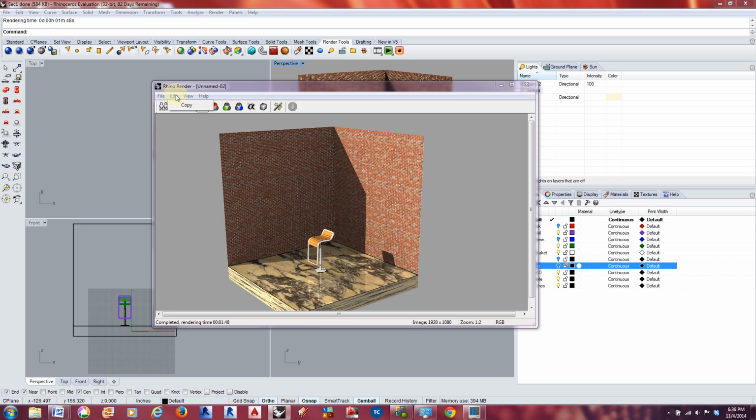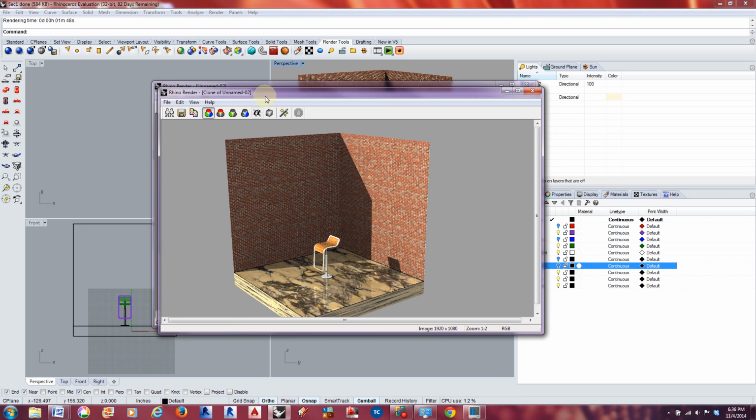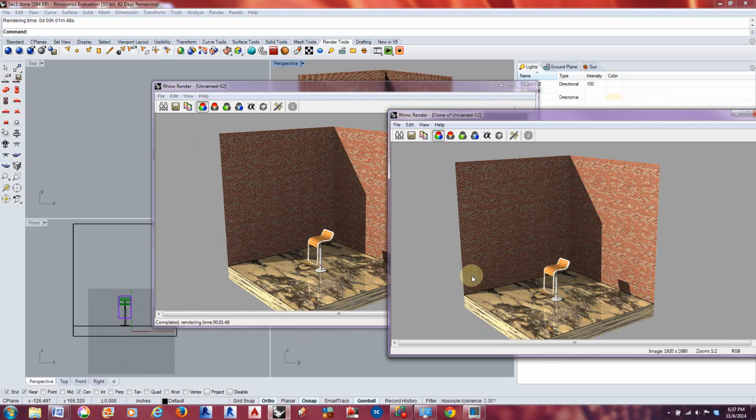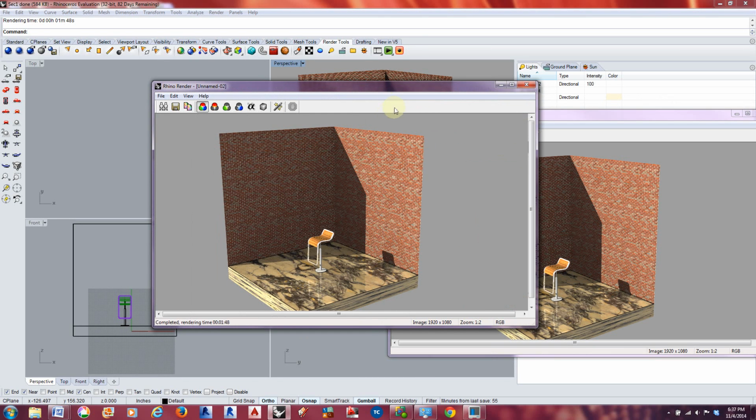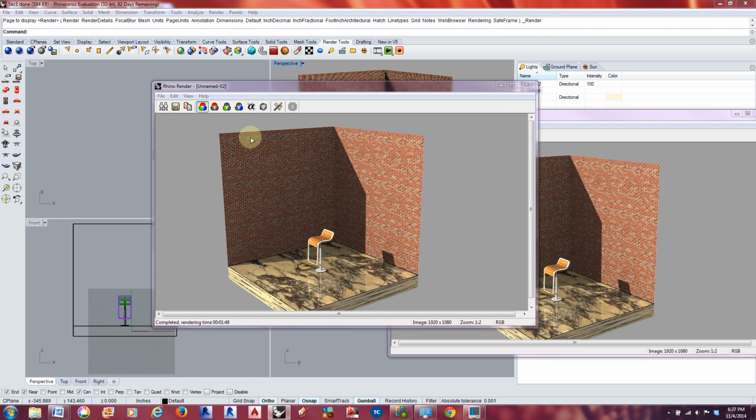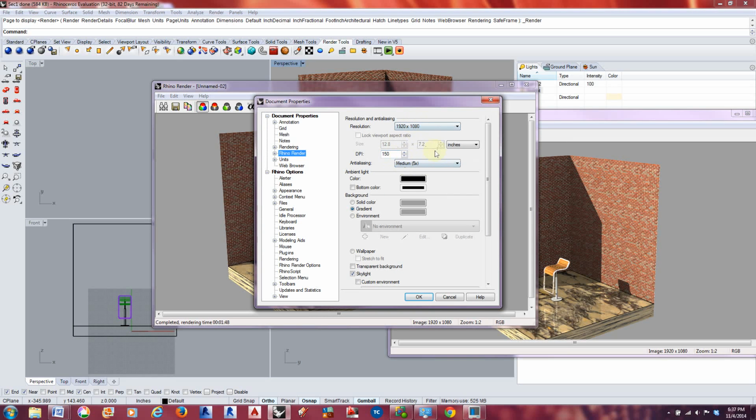The other thing that you can do is you can clone it. So if you were working on a render and it wasn't quite right, you could clone the render and then make adjustments, re-render, and compare the two and say, okay, where do I need to keep making these small incremental adjustments, maybe in this particular material or that particular material. If you're in that stage of perfecting your render, you probably don't want to render it as a large image yet. You want to work on a small image first to get it right, and then go ahead and do the larger image. So it's just a matter of setting these to something smaller so that the renders happen quicker and you can run through them.